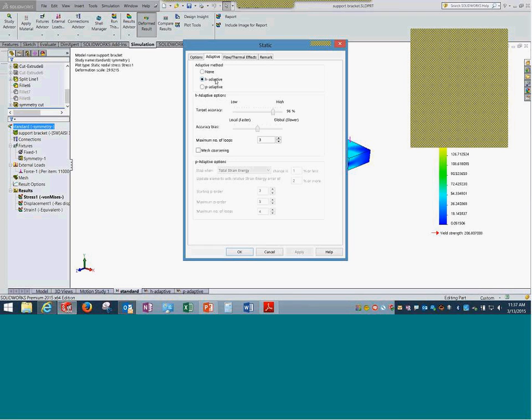Second, typically in assemblies or contact where there is a huge number of contact sets, again it does not make sense, because the number of iterations can be huge. Other than that, if it is non-linear, the software itself does not prevent it, but it does not make sense, because solving one non-linear iteration itself takes a huge time. It might take a comparatively large amount of time to solve, and again that does not make sense here. So in these few cases, have good judgment.